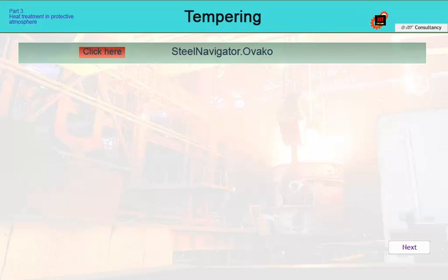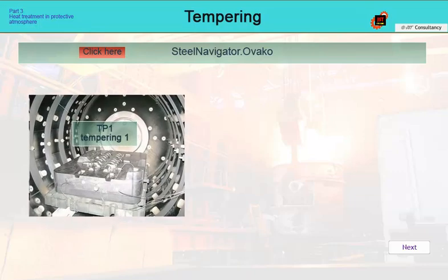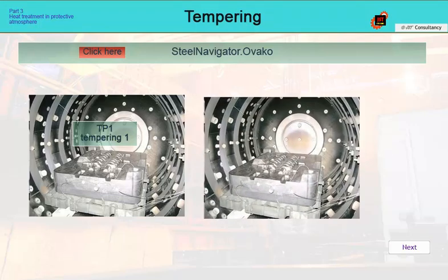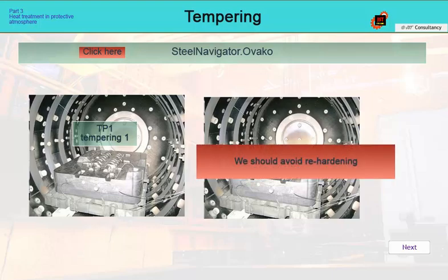in hardening and tempering. However, if we are going to temper, it is good to think about the so-called rule of caution. This rule says that if the result is not completely verified, it is better to start at a lower tempering temperature so that the hardness does not fall below the required value. In that case, we would either have to ask the customer for an exception from the required parameters or re-harden the parts. However, re-hardening the material carries certain risks, and we should avoid them.